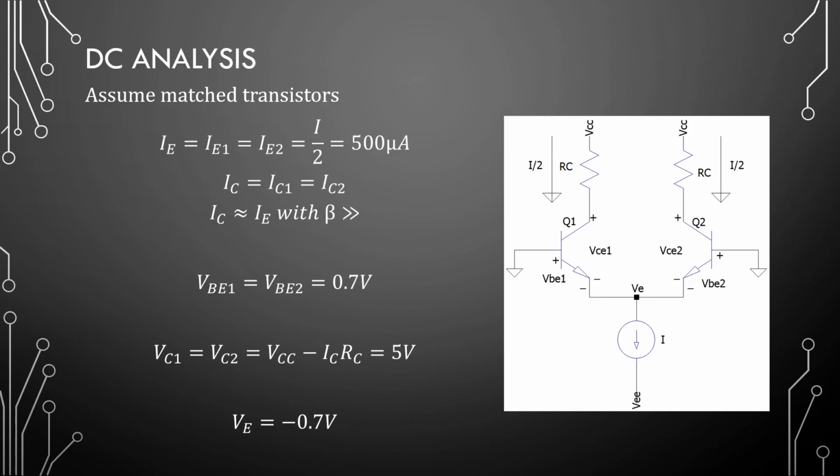So first we will have a look at the DC analysis of one of these amplifiers. So if we have a current source down here at 1 milliampere and we ground the two inputs, the current will divide equivalently between the two half circuits, and that means that we will have 500 microamperes sitting on each side.